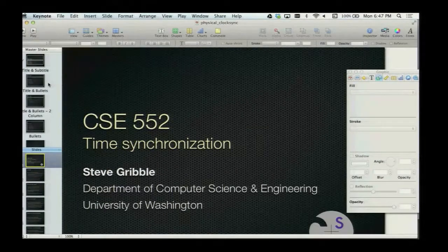If you measure that electric field and then amplify it back in, then applying an electric field to that actually accelerates that oscillation. So basically, by introducing a feedback loop into this mechanical device, you can get this crystal to oscillate according to its dominant mode and to produce an oscillating electric field according to its dominant mode. And that's basically now a regular signal that you can then use to drive a clock. It's basically like that, exactly.